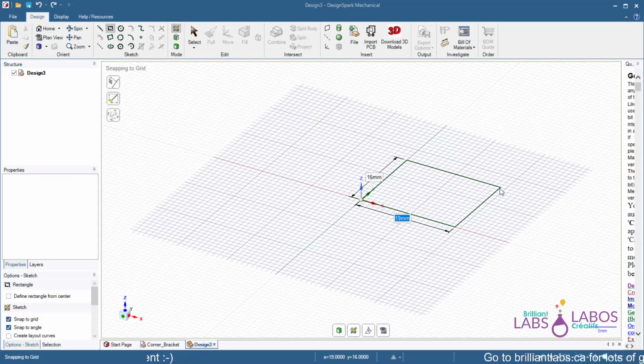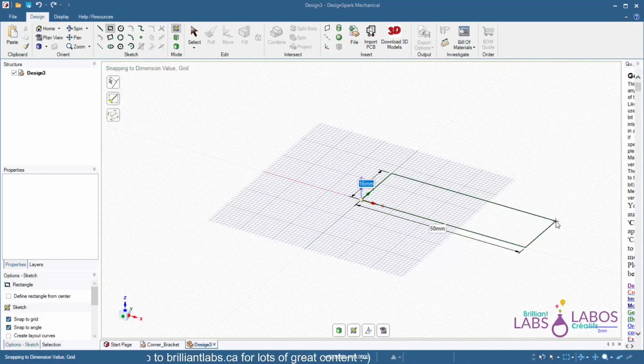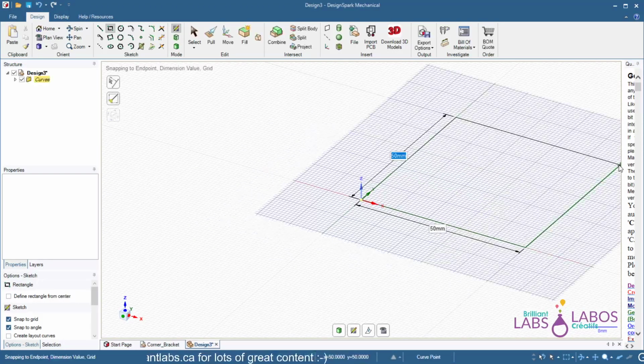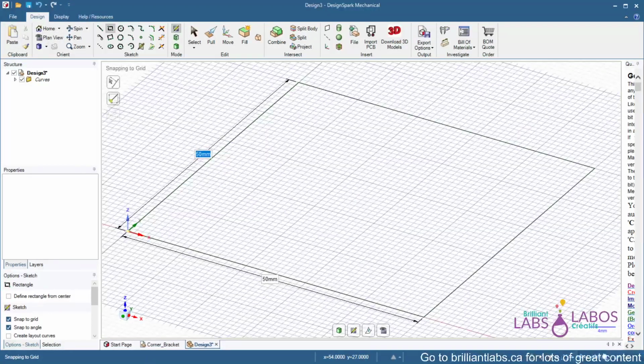That's 50 millimeters. Just like in Tinkercad, if you've used that before, the standard unit of design is typically millimeters. So I'm going to type 50, and I'm going to hit the Tab key. The Tab key will take me to the other measurement. And I'm going to put 50 in there as well. So now I have a rectangle that is 50 millimeters by 50 millimeters. And I'm going to hit my home button again so that I'm in a little closer.